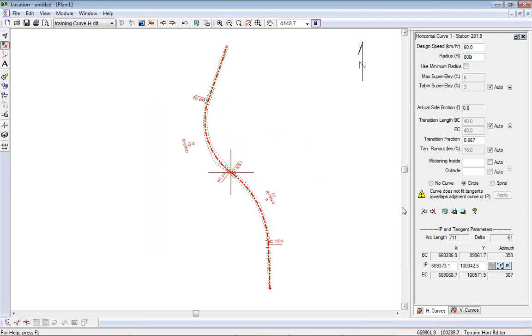Yeah, okay. So now if I change something here, like type in 600, yeah, that's better. Now it says 3.0. Okay, so you can set any radius you want. You can also set any speed. So if I increase the speed of my road to 80 kilometers per hour, then I'm going to get different warnings because it's going to look that up in the table.